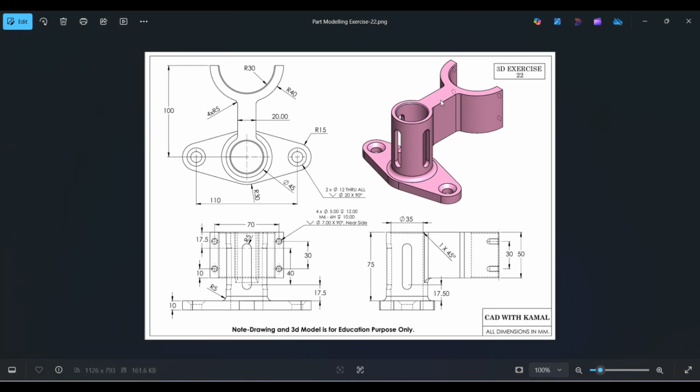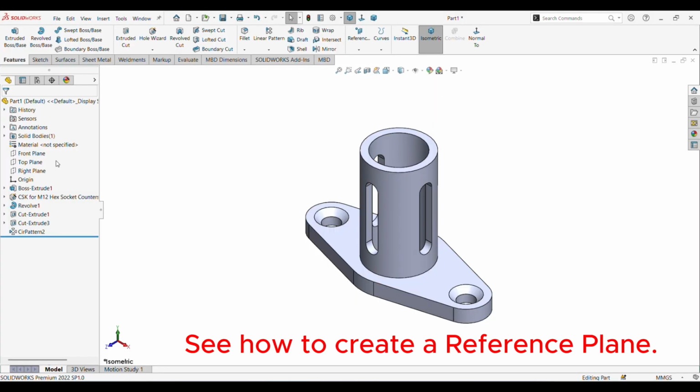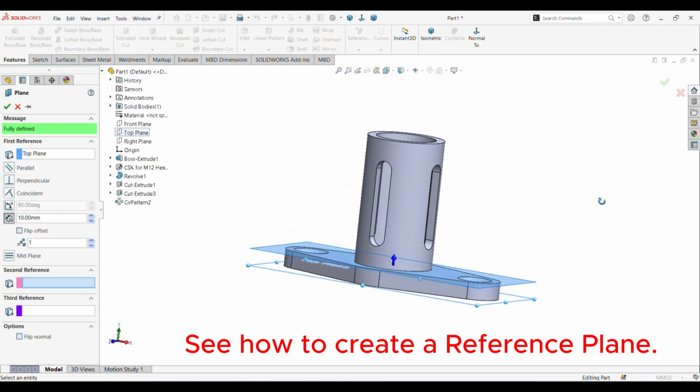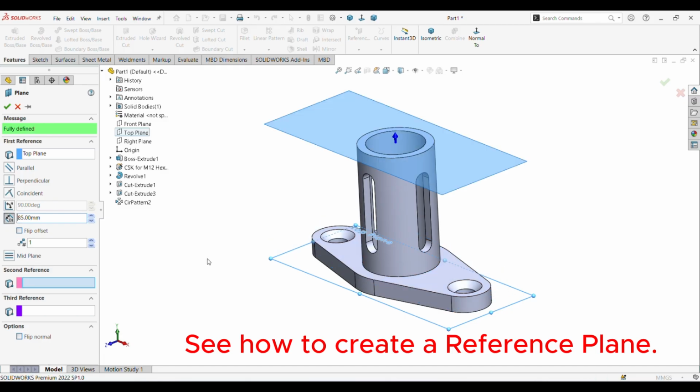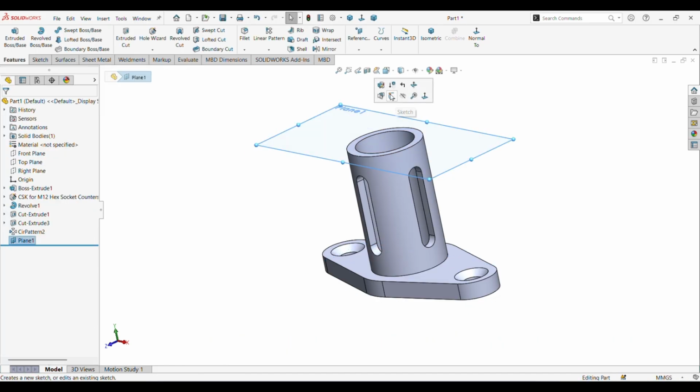Now we need to create this body. So this body thickness 20, R30, R40, and from this center to this face 100 mm distance. Okay, so select this face, or you can select top plane, then you can create an offset plane 10 and it is 75, so you can use 85. You can create plane also, all are same. Okay, you use this plane sketch,